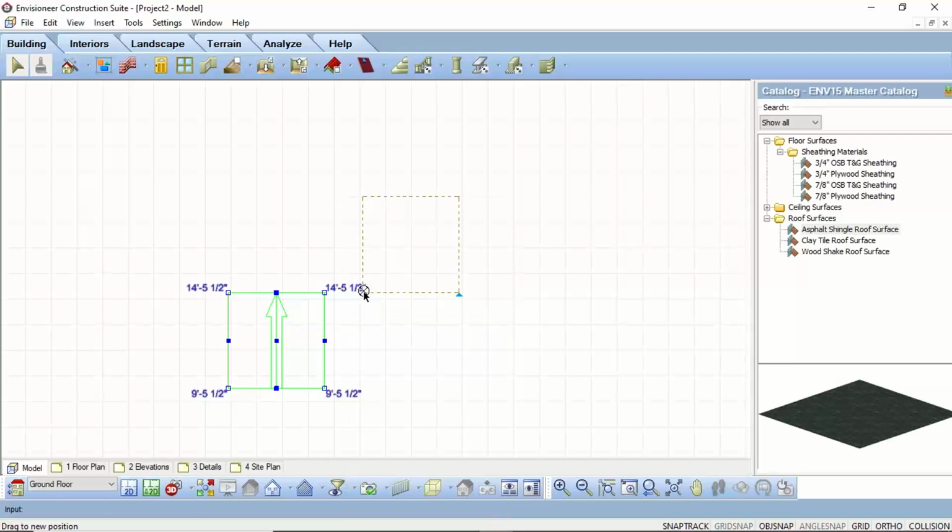And this is going to bring up another command that we can use, which is called the Intersect Planes option. So we're basically going to be joining two surfaces together. So you can use the Intersect Planes tool to join two surfaces together. To join two surfaces, you select the edge of each surface that you want to extend. The Intersect Planes tool calculates the plane where the two surfaces would intersect in space and extends the surface edges to this plane.